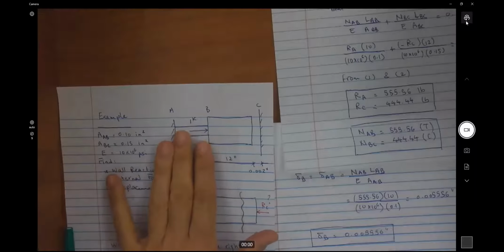What did we call these type of problems in solids? When equations of equilibrium are not sufficient and we need compatibility equation. Remember? No, superposition was to look at different effects and add them, right? But we call these, when the unknowns are more than the equations of equilibrium, indeterminate problems. So this is the problem we just solved.